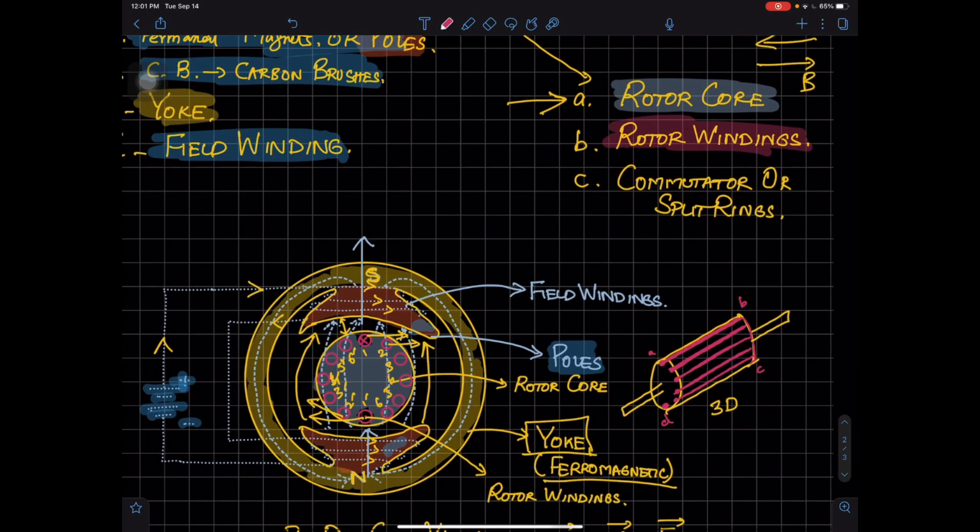So in the rotor parts, you have the rotor core on which all these windings have to be done. And then the rotor winding, certainly, that is the loops over here. In this motor, I have shown you just 6 loops. It can be even 100 loops. So for big machines, it can be 100, 200 loops over there. The greater the number of loops, the difficulty increases for the winding design, but also it increases the amount of torque being produced over there.